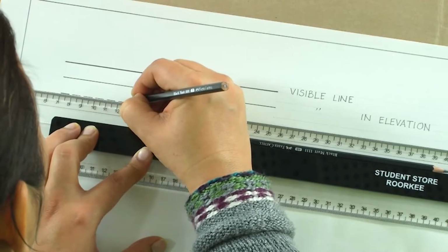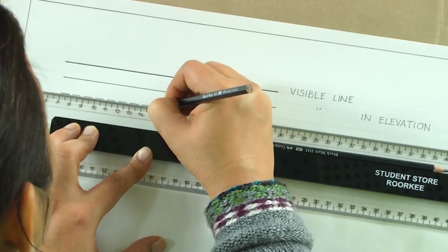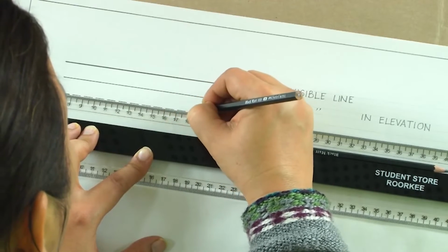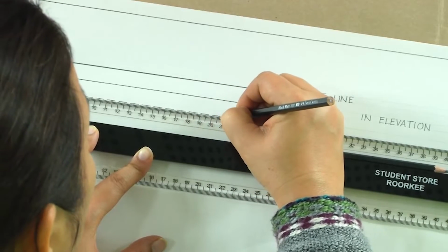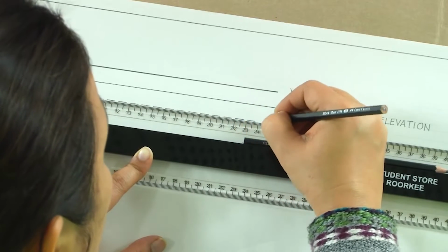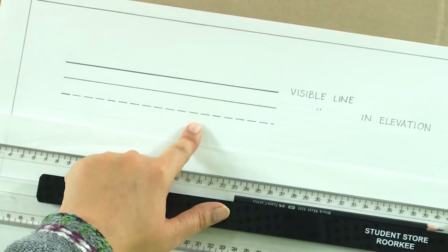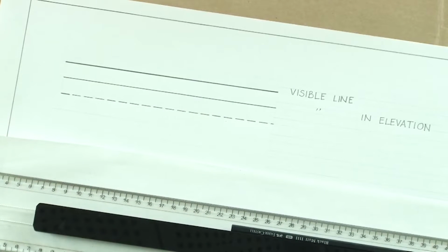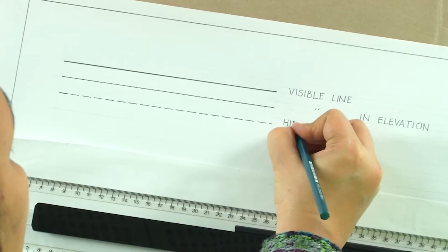This is again a thin and a dark line. So, there is darkness in it, but it is relatively thin as compared to the visible line in section. So, if you draw for architects, if you are drawing a staircase, the steps of the staircase on the first floor will actually be seen in this line, which is the hidden line, and it is also called the dotted line. So, here we will use the nomenclature as hidden line.